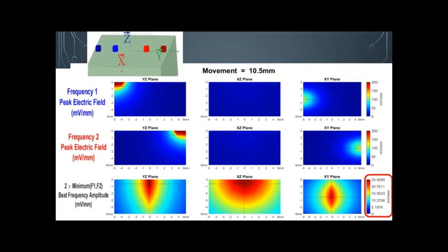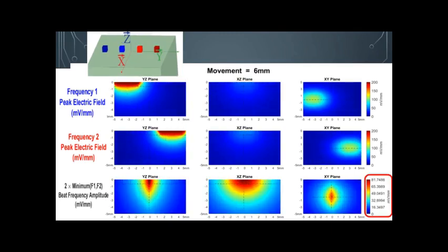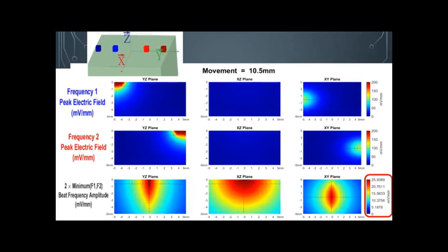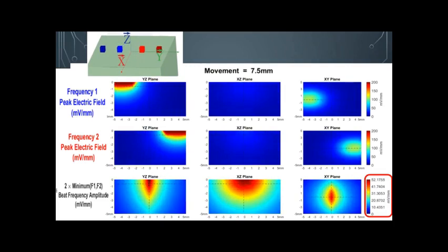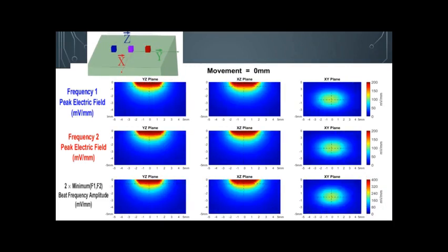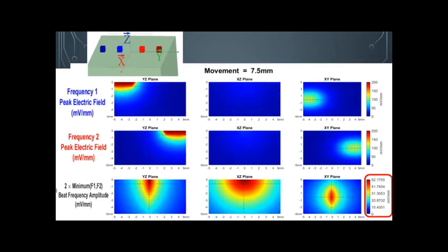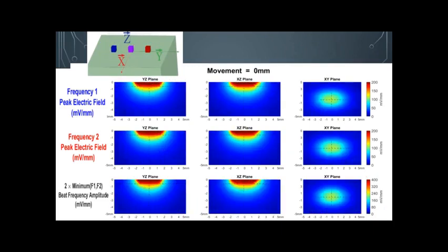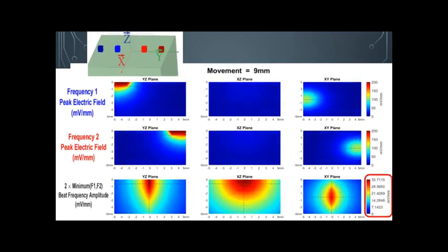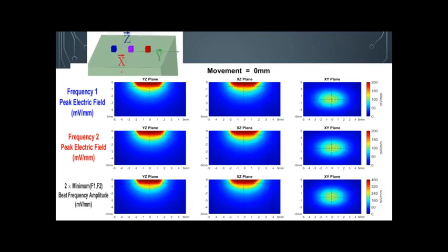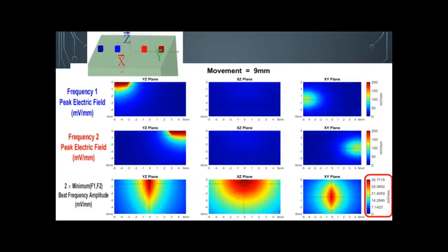As can be seen, as the midline distance gets larger, the electric fields can penetrate further into the medium. Also, something to note is when the distance gets large enough, the maximum electric field of the beat frequency gets smaller and smaller, as seen in the axis of the color bar to the bottom right, outlined in red. Therefore, if one needs a certain level of intensity to activate neurons deep in the tissues, one may need to raise the intensity of the original current injection to an unreasonable level.